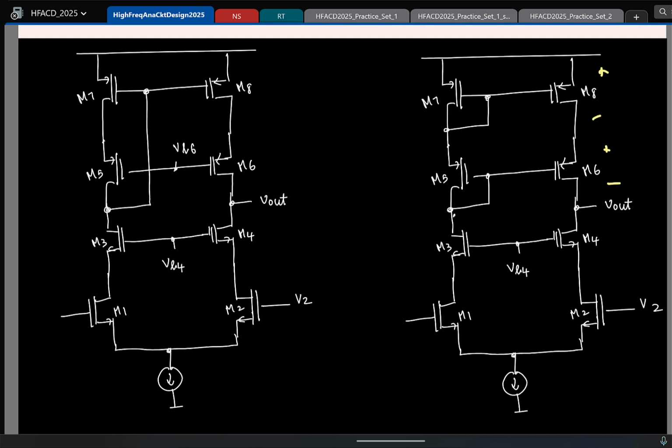In the first thing that we argued that Vout and the drain of M5 are the same, right? And also that the drain of M5 is connected to the gate of M7. Correct. So isn't that drain fixed like VDD minus VSG7? That is at the operating point.